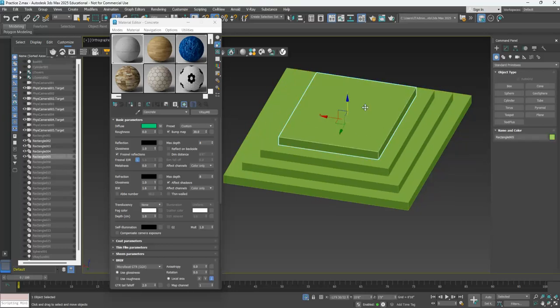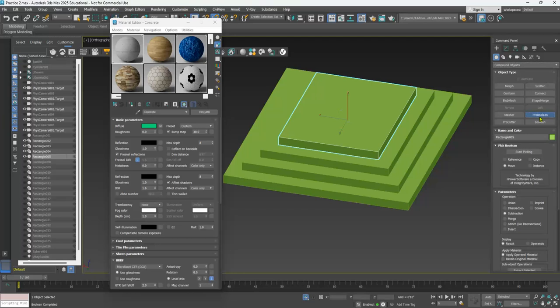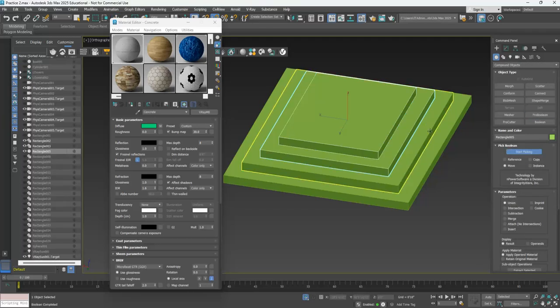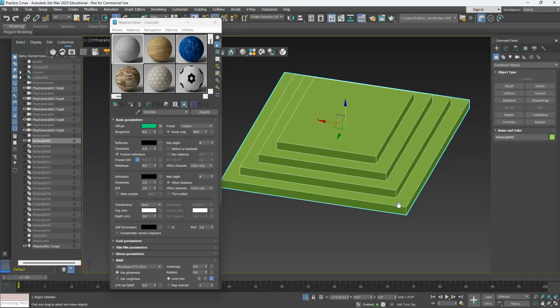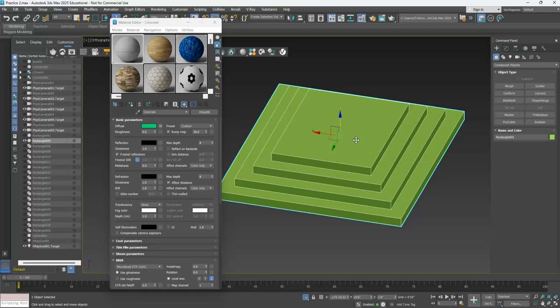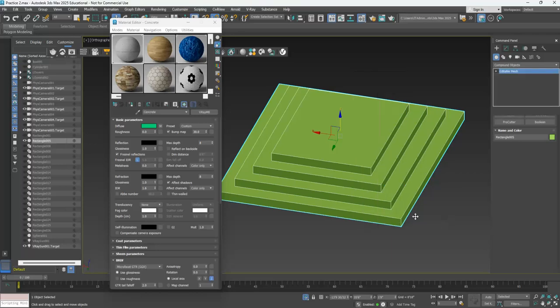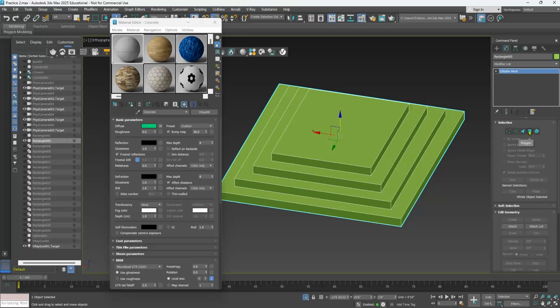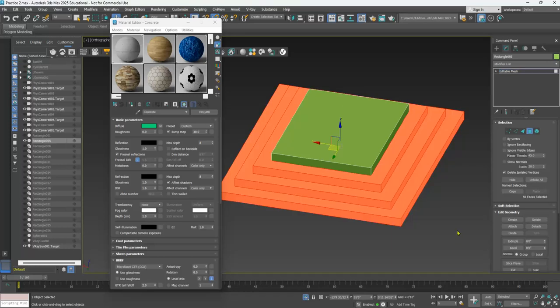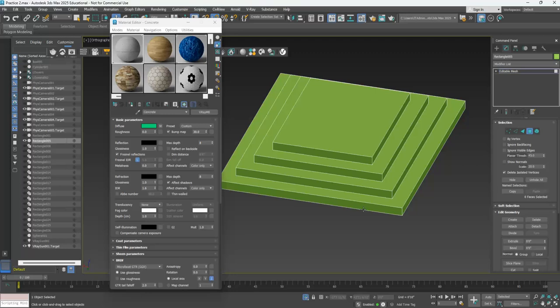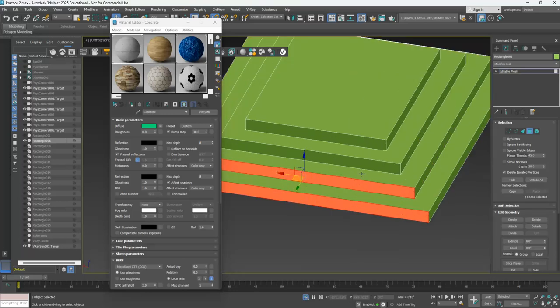So let's say I start with this shape here, and I go here to the plus, the circle, go to compound objects, and go to Pro Boolean and do union, and start picking. So now it's all one geometry here. Next, I would select it, right-click it, and do convert to editable mesh that we did before. Next, I will go here to polygon, and I will kind of separate these things. So I will pick the vertical ones here, do control.